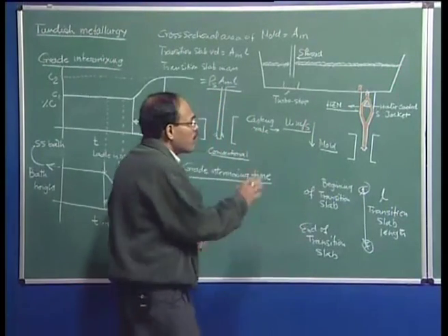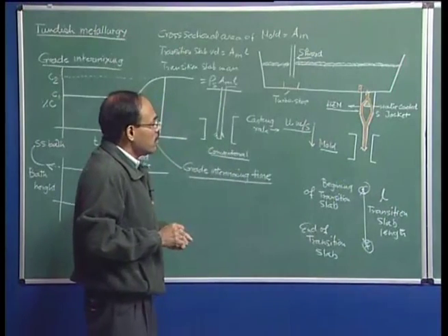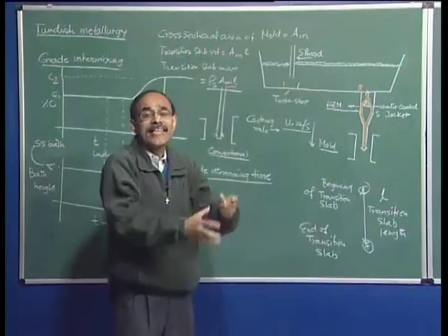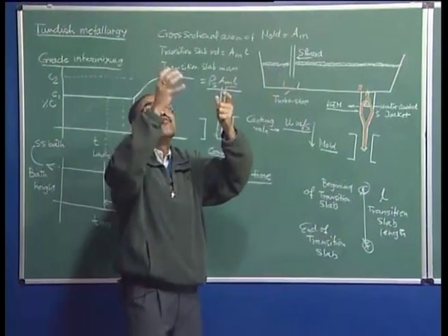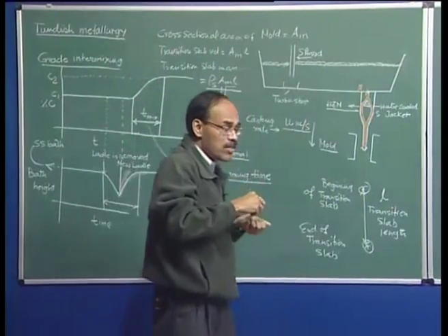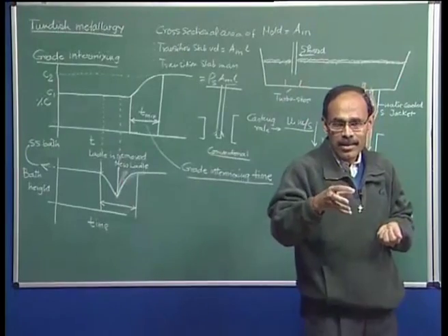Now, if the velocities are higher for a given cross sectional nozzle diameter, you can imagine that the flow rate is very high, and in that case there will be a tendency to form vortexes or draw the slag layer. As I have mentioned, you can see the funnel vortex, particularly when you are draining a sink.